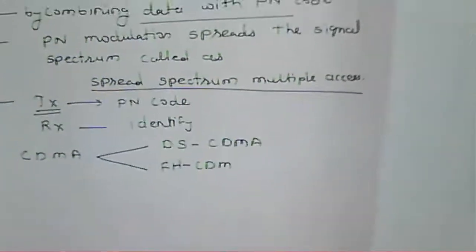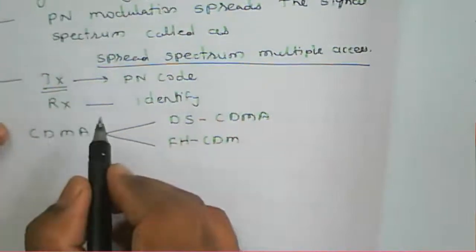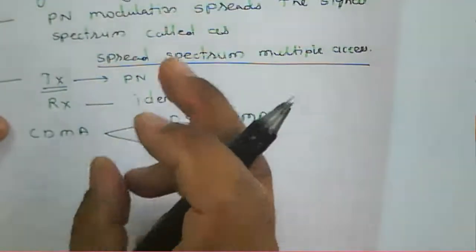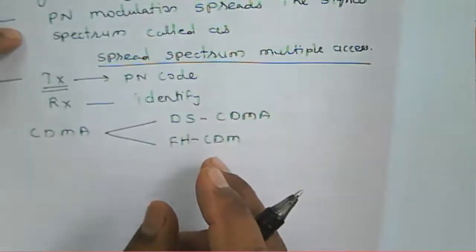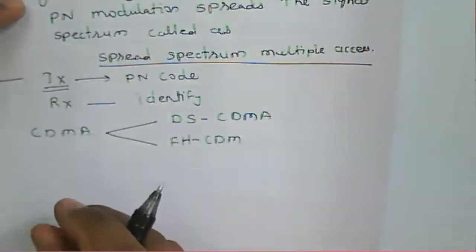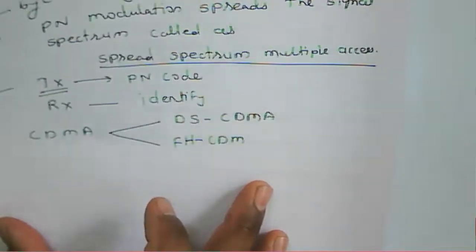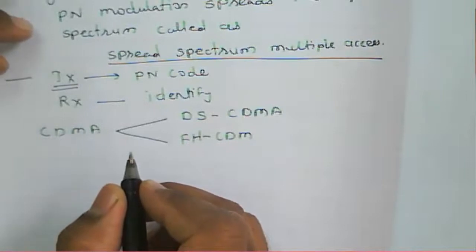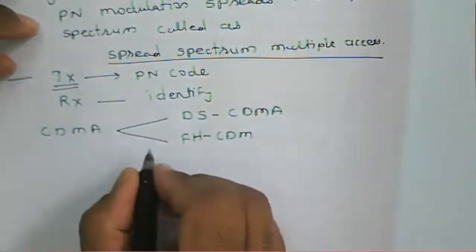Now, for a given length of PN sequence, we generate the PN code. How do we generate that PN code? We use a modulo adder, or simply we have the polynomials of that particular PN code, and then we can design the PN code using a shift register. That PN sequence is nothing but a modulo 2 addition, and that is to be used here.